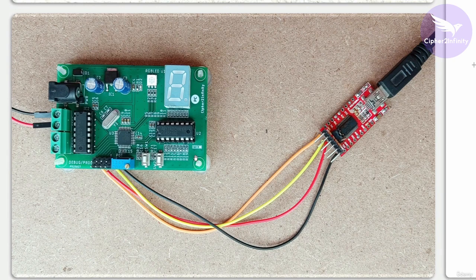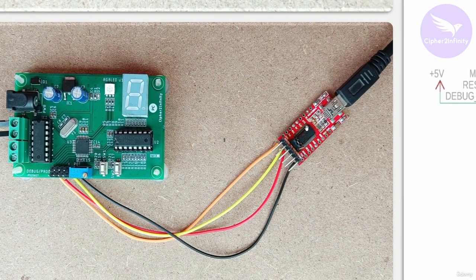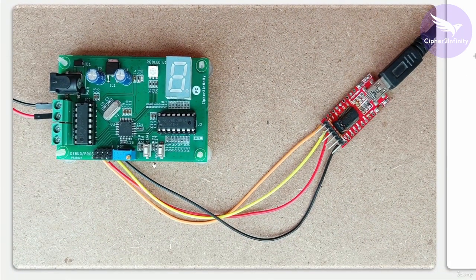So in order to do the communication between the microcontroller and computer, you just need 3 wires, which are ground and the RX and TX wires, okay? Whenever you send data from the controller, it travels through the TX pin, then it will be available on the RX pin, then through this USB to UART converter, it will travel through this wire, and then you will be able to see that data on the computer, okay?